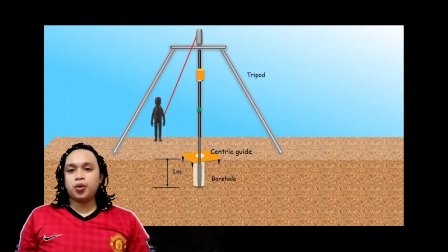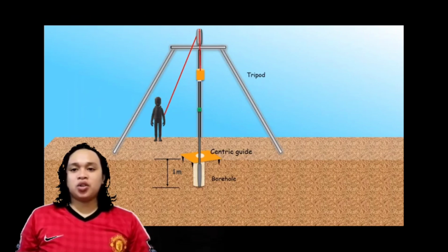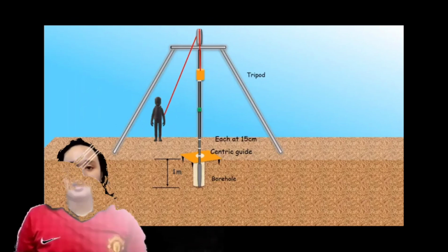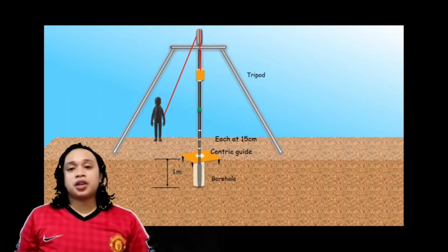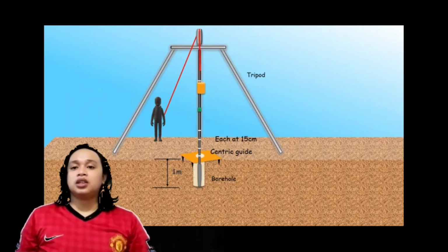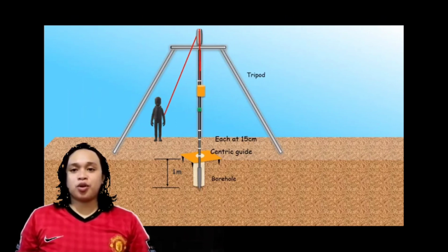The test will be repeated in a number of boreholes covering the site, depending on the building area, the importance of the structure, and the variation of the soil properties across the site. The standard penetration test values are presented either in the form of a table or in the form of bore log data.